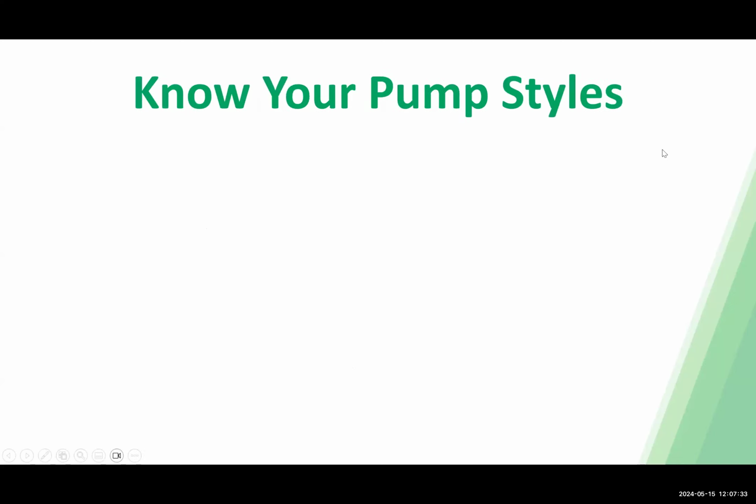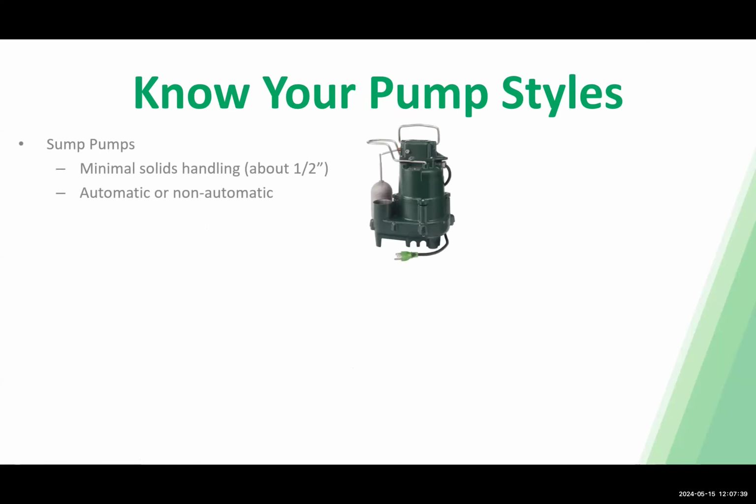So first, we need to know our pump styles. The first pump we're going to go over real quick is sump pumps. These have very minimal solids handling capability, up to about 1/2 inch. The main reason why you need that is for any kind of solids that you may find in the groundwater. And these pumps come in automatic or non-automatic.